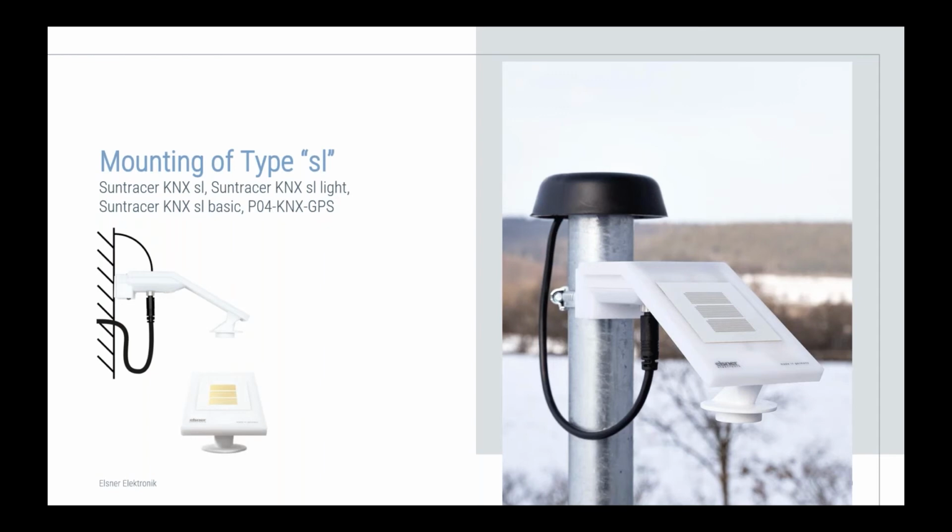It is very important that in order to measure the wind direction and the wind speed correctly, the weather station has to be located on the lee of the facade. Therefore, the installation on the facade only makes sense if shading sits on the same facade. Furthermore, the weather station can be mounted with the help of a boom to set off from the facade.